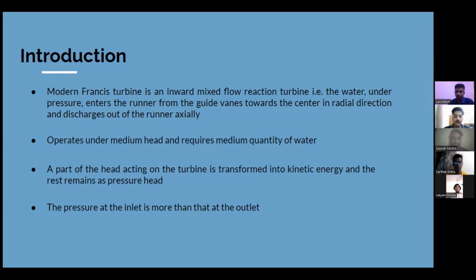In these plants, high pressure water enters the turbine through a snail shell casing. This lowers the pressure as the water curls through the tube, but the speed of the water is maintained. The Francis turbine is the most common water turbine in use today. The speed ratio of the Francis turbine varies from 0.6 to 0.9. These turbines are divided into two types: inward radial flow and outward radial flow. The Francis turbine can be built in the form of a radial flow turbine.